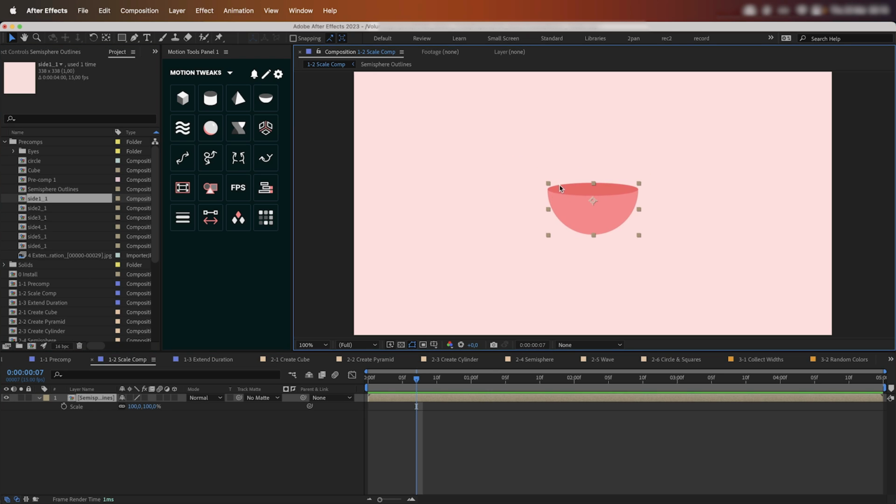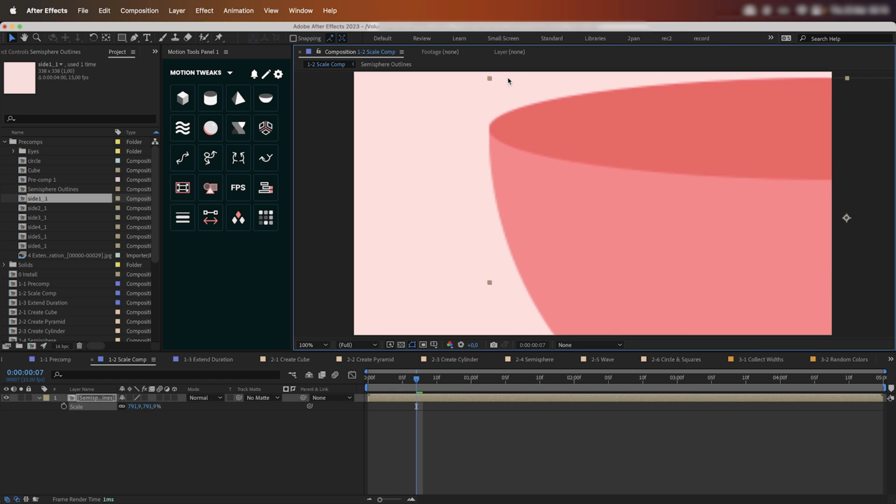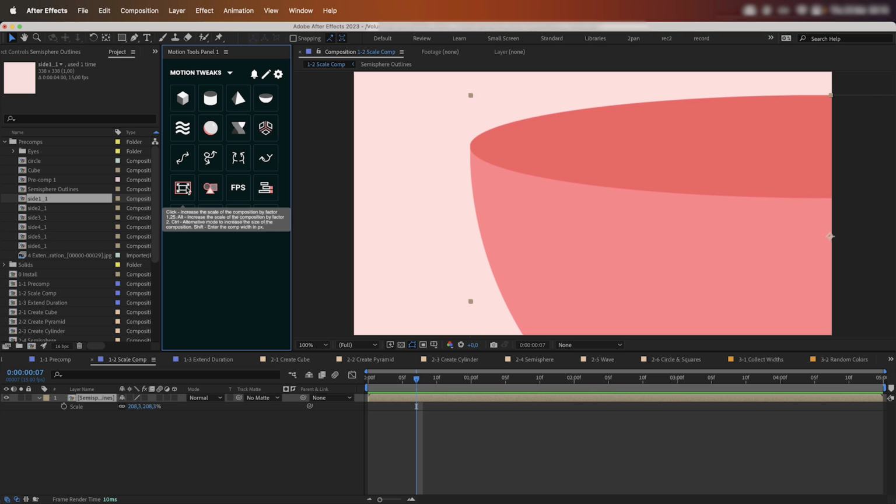Let's say you have a few small compositions and you realize that you need to increase their quality without using continuously rasterize. By clicking the script, you'll increase its size and proportionally reduce the scale. As a result, the layer remains as it was, but it gets better quality. This will allow you to quickly increase quality during animation.